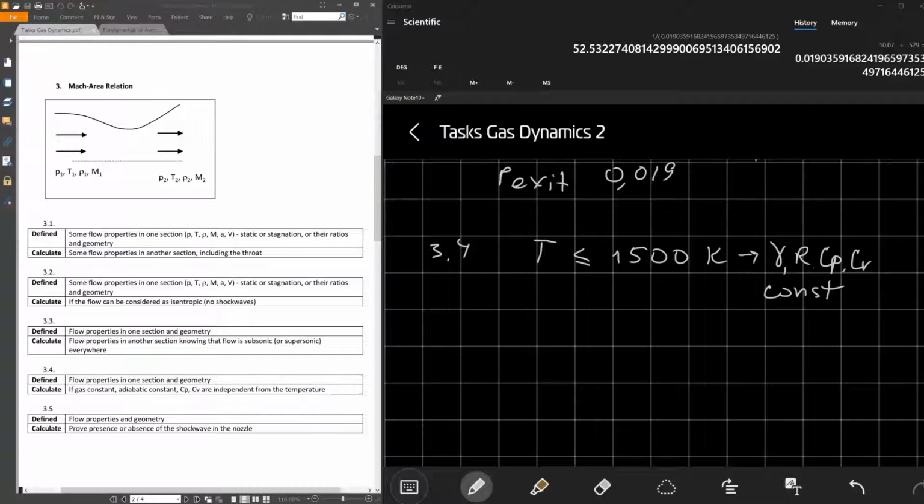Usually it happens when the flow is completely stopped, so it corresponds to stagnation temperature. So basically, we just need to calculate the stagnation temperature at this section. I will show you two examples that have different initial parameters for this calculation.